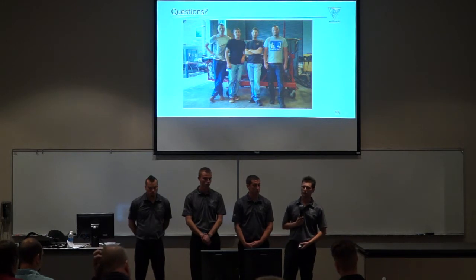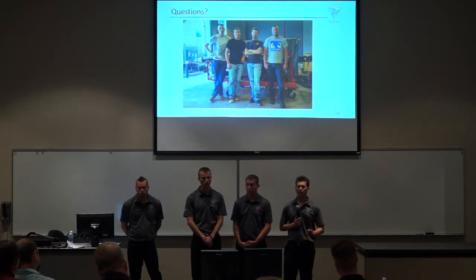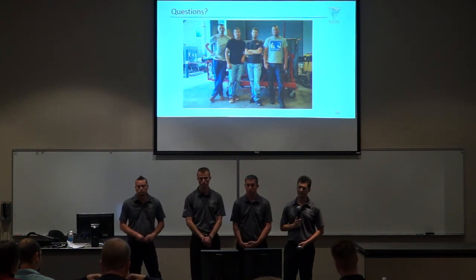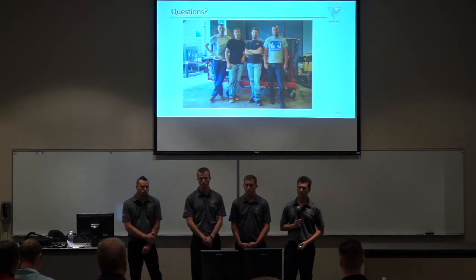I think the big thing we got right, we used the same entrance and exit angles of the nozzle, based on the fact that we used a compressor map to map out what we thought the turbocharger was going to produce as far as the pressure ratio goes. That was an experimental part of it, being that it's an uncoupled system for the turbocharger. It didn't react like we expected it to. We sized it based on our mass flow coming out of that. We found that that was inaccurate, the way we assumed it was going to behave.